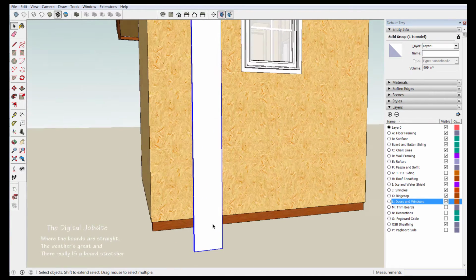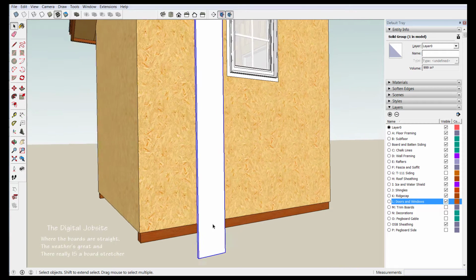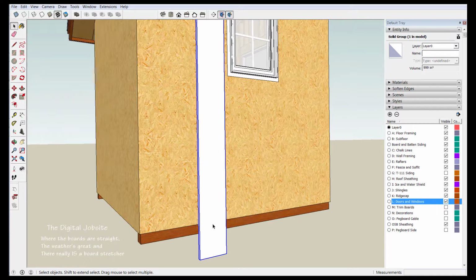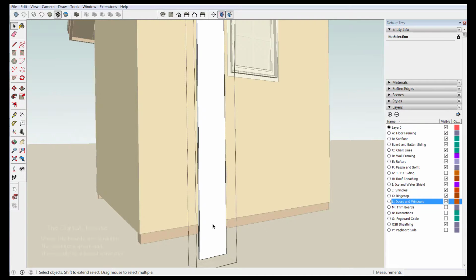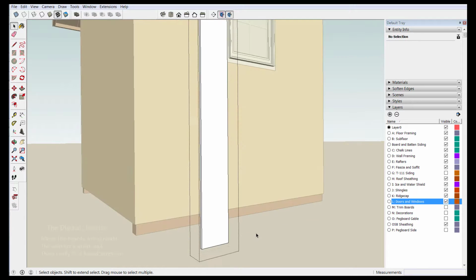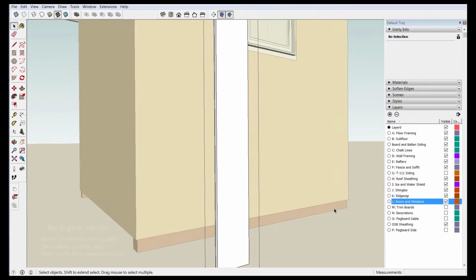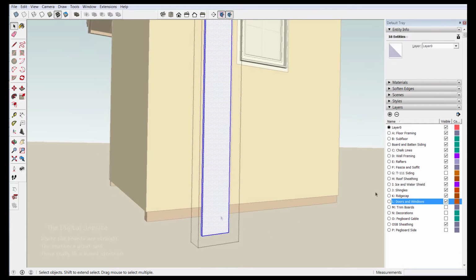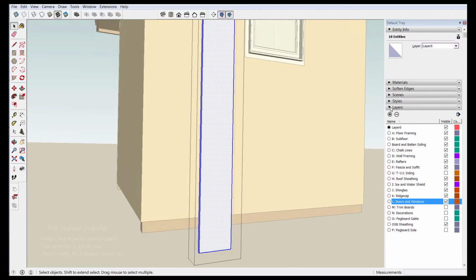As I said earlier, we don't need the attributes of components for this siding in this case, and they need to be grouped. So I want to make this look like a piece of siding to start off with, because after it's in place, I can't change a group of groups in the same way that I could change a group of components. I think that'll make sense as the video goes on. So here's a piece that we're going to use for a piece of siding.